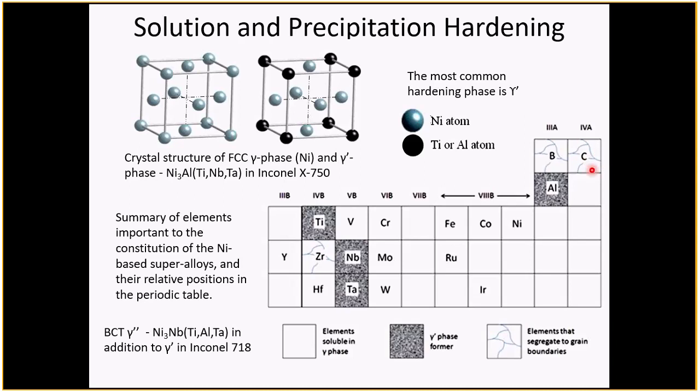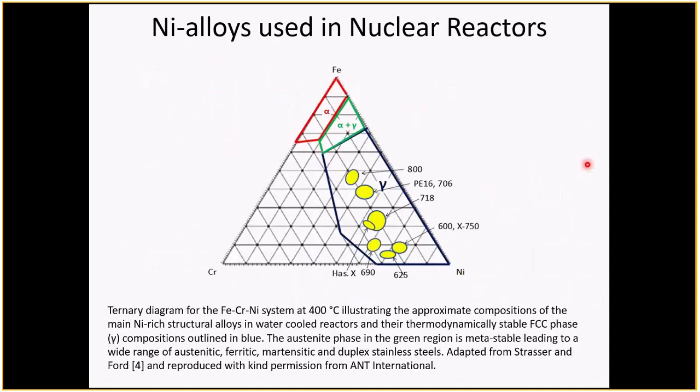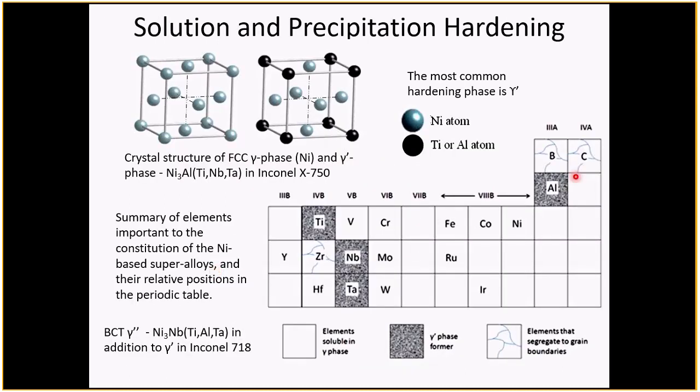Unfortunately, when you heat treat nickel alloys containing sufficient carbon, the nickel alloys contain chromium, and what happens is that the combination of the precipitation of the carbides on the boundaries, typically the carbon reacts with chromium to form chromium carbides.